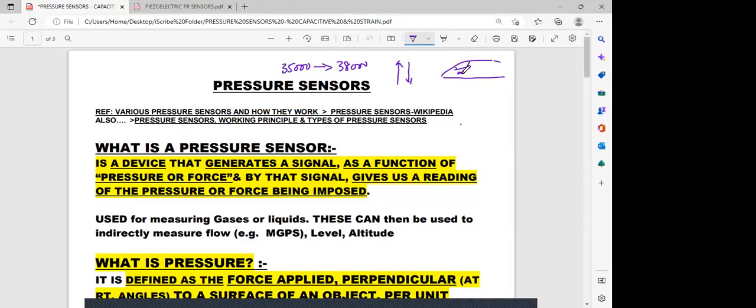So he was getting a wrong altitude, where the traffic controller had said you have to be at so-and-so height. As they were passing along there, maybe the Morocco ATC said you are good to go, but he was looking at, say he was supposed to be at 38 and he was getting 35,000. So what did he do? He had to correct that because he was reading it from this pressure sensor. He started to put the nose up, and the aircraft started going up, whereas your starboard sensor was giving the correct altitude.